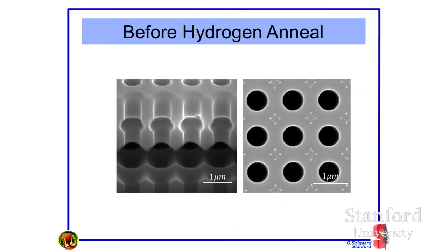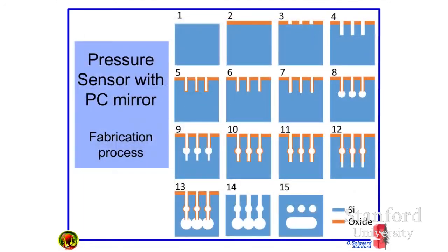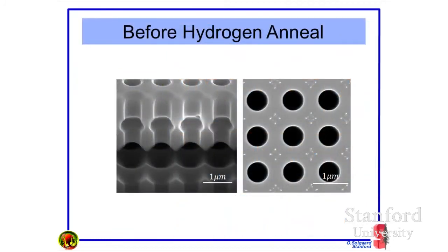So this is before, this is at level 14 in the fabrication process, where we now cut out so you can see what it really looks like. There is this hole down in the silicon. There's a spherical hole sort of partway down, and then there's a void that is continuous, that stretches from hole to hole further down again. The top you can see is just these cylindrical holes.